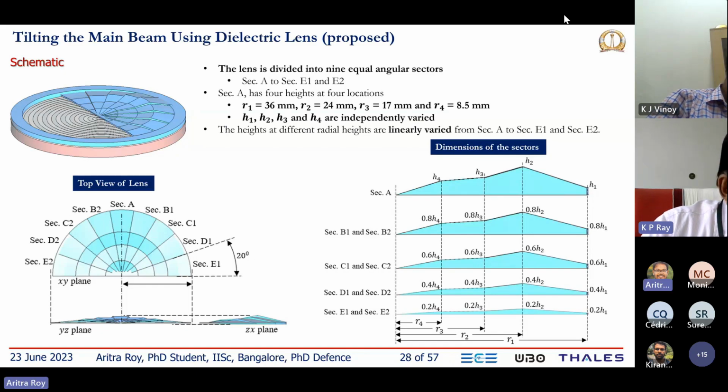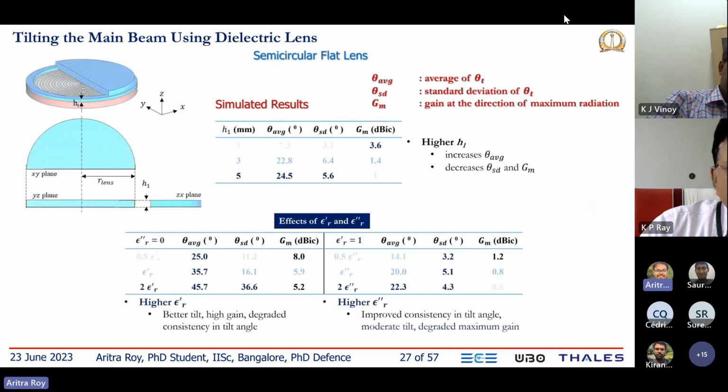Do you think so? Sir, actually, we first simulated the flat lens, then we simulated the exact structure that you just described. In that, we linearly increased the lens thickness with frequency, maintaining the minimum height close to the high frequency and the maximum height close to the low frequency. That was the geometry we investigated, but we skipped it here to make it coincide. In that part, obviously, we got a better response compared to a flat absorber.